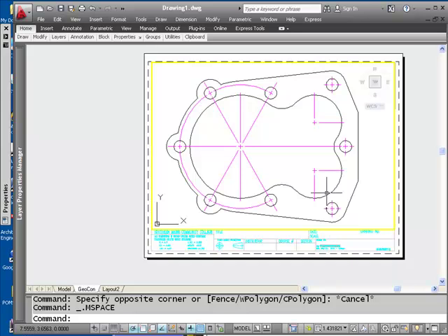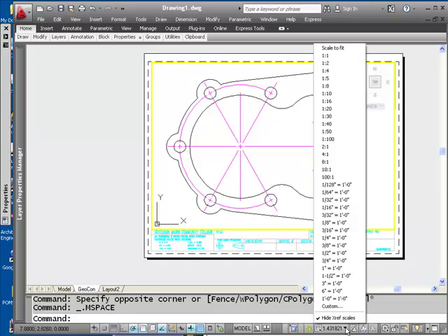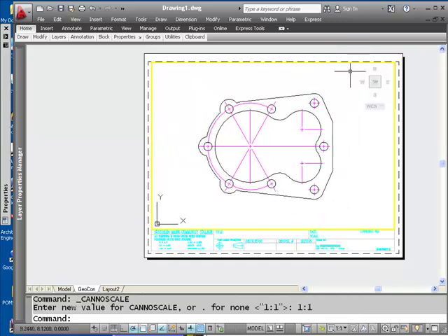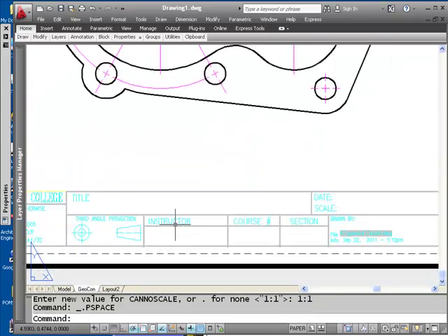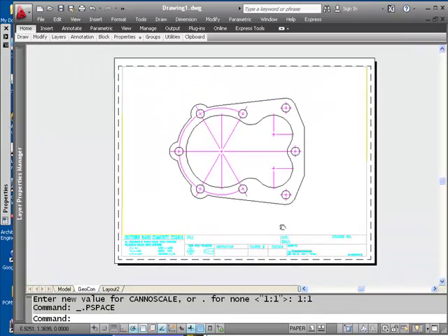But now, with this gasket, which is a part, I have to use a plot scale. So if you look at the bottom on the status bar, I'm going to select it, and instead of accepting 1.431821, which is not a plot scale, I'm going to go and pick 1:1, makes things a little bit smaller. Pick the padlock button, and then you just have to go in and add all the text to your title block and then submit it.